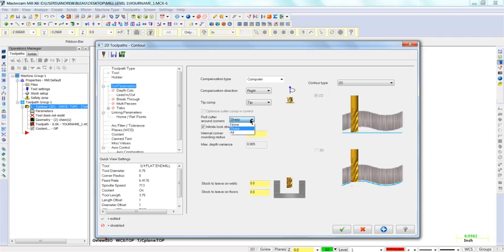Roll cutter around corners set to sharp inserts arc moves around the corners in the toolpath. The radius of the arc moves is equal with the radius of the tool. Infinite look ahead prevents the toolpath from crossing itself. Stock to leave on walls and floors leaves a specified amount of material on the part to come back with a finish pass. Contour type sets the type of contour toolpath. There are 7 different contour types based on the selected geometry.